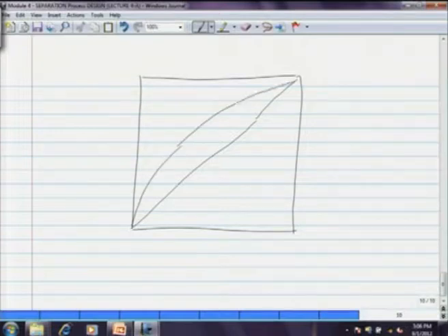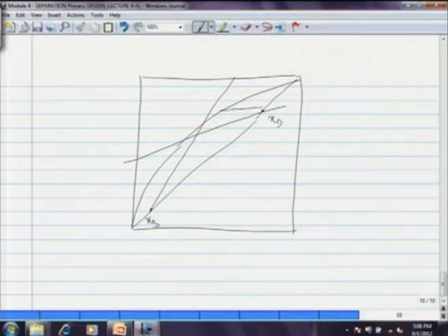So, in a McCabe-Thiele diagram, which typically looks like this, this is the y equal to x line, the diagonal line, this is a VLE curve, and then you start calculations from given x_D and given x_B, and then you make out the number of plates. Okay. So, we have considered only this portion, the portion which I am now hatching in red.